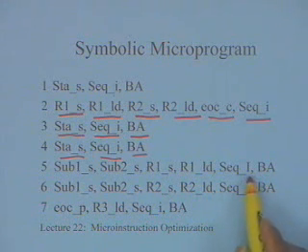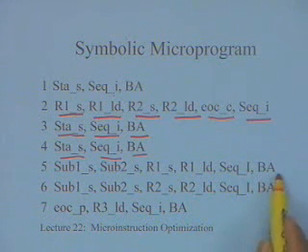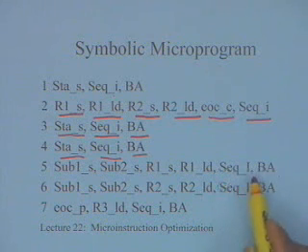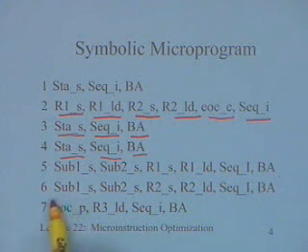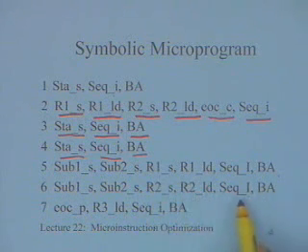So here what I am going to do is an unconditional jump. So sequencer instruction will be unconditional jump and the branch address. Status select is not there, but similarly I am going to do everything else the same except that R2 select and R2 load, sequencer instruction and branch address.